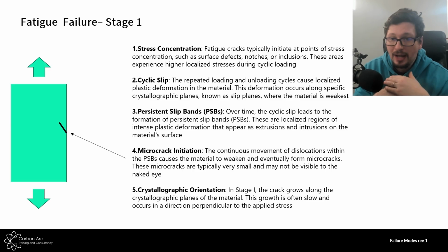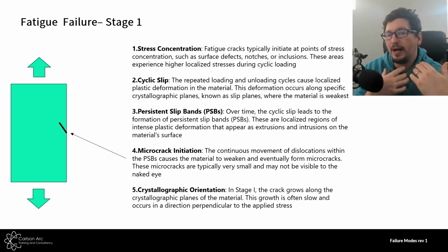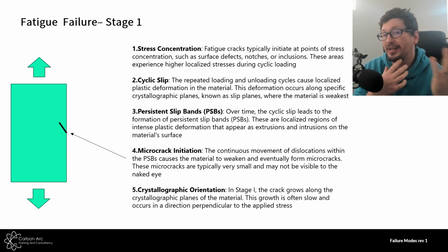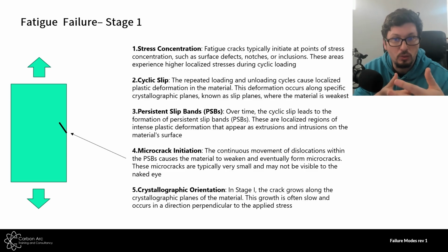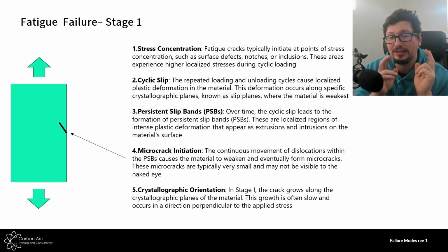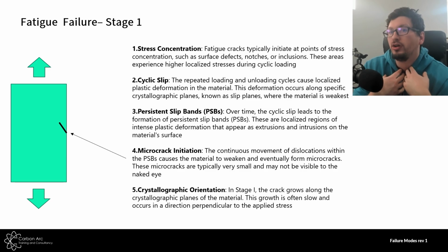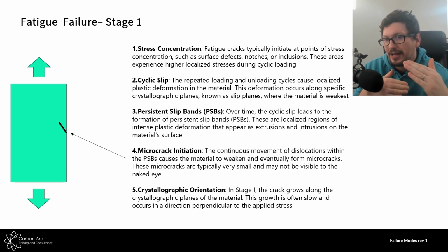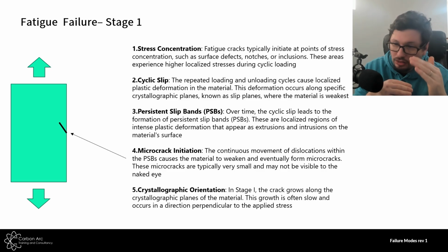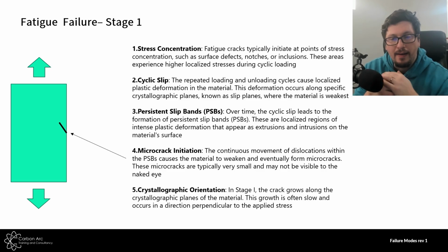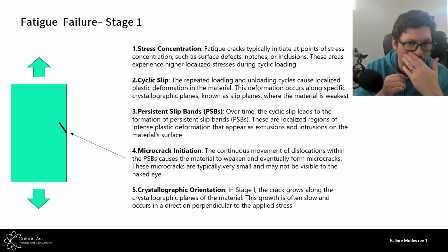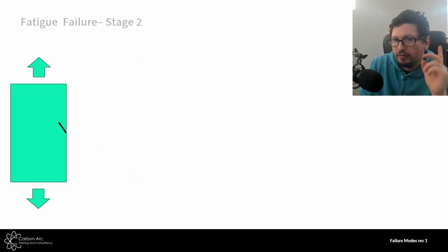This is something that will happen everywhere, but of course is brought on more if you've already got, say, micro cracks already existent in the surface of the steel, maybe a high stress concentration, like the toe of the weld or a crack from your welding process. But even in material which is inherently what we would say perfect, eventually these micro cracks through stages 1, 2, 3, 4 will appear, and this will happen. Okay, so that's our first stage, producing that little 45 degree crack.